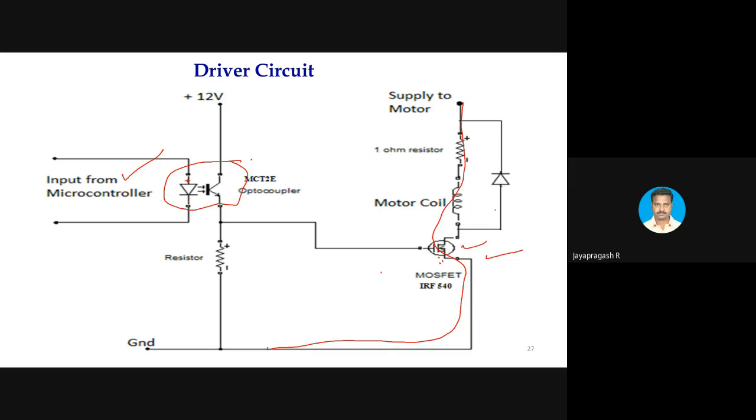It is also mandatory to provide a freewheeling path. Once you turn off, the energy in the phase winding will get discharged through the internal resistance of the freewheeling diode and the internal resistance of the winding. The freewheeling diode will get forward biased, and the energy remaining in the winding will get dissipated in the form of heat. I know we are not utilizing it properly, because our aim is to find only the aligned inductance. I am not using this circuit for regular operation, so I used this simple freewheeling circuit.